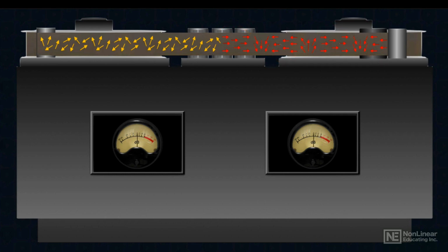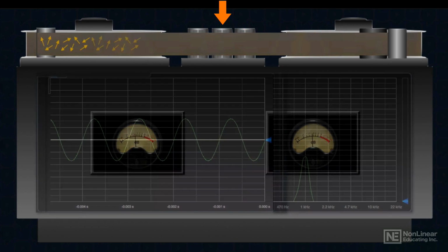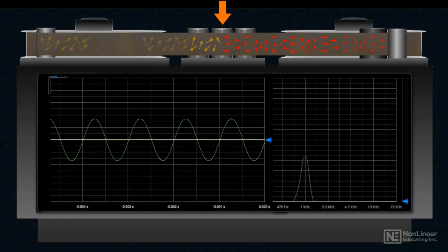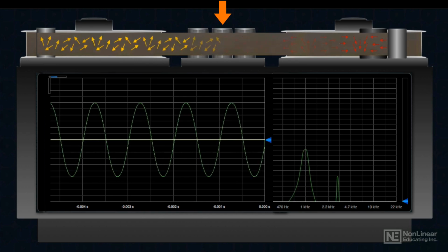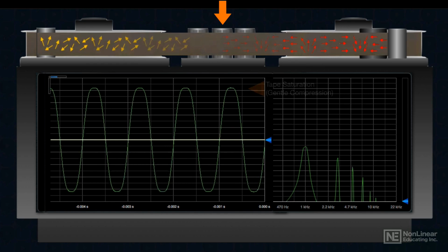The magnetic particles consist of domains. On a blank tape, these are randomly oriented, but as the tape is magnetized by the record head, they're reoriented to follow the polarity swings of the incoming magnetic flux, the incoming audio signal. The degree to which these particles retain the new magnetic state depends on the strength of the incoming signal. Weaker signals will realign only some domains, or a correspondingly lower recorded signal level. Stronger signals will magnetize more domains. When all the domains are magnetized, the tape is saturated.